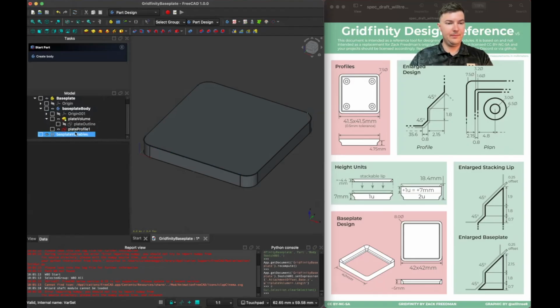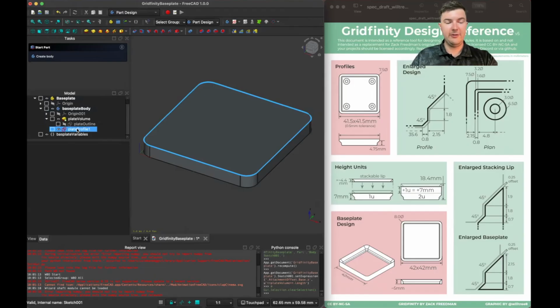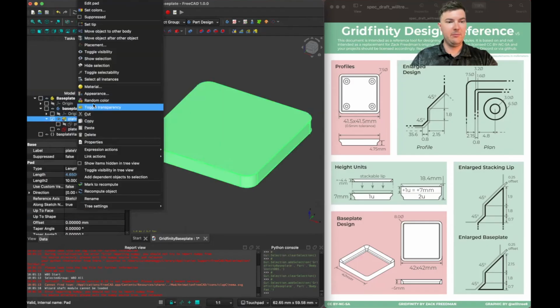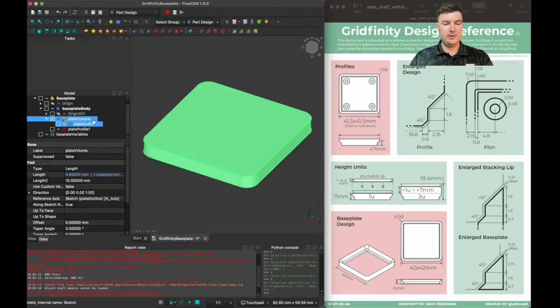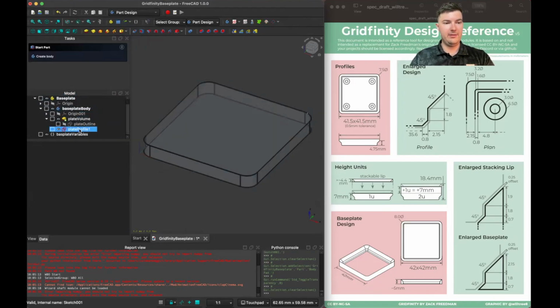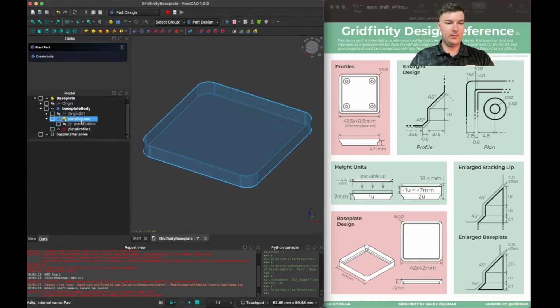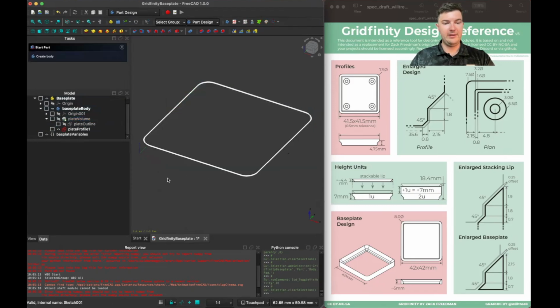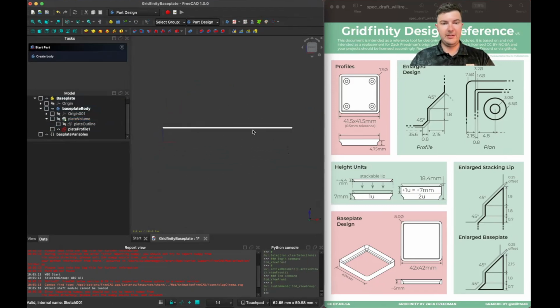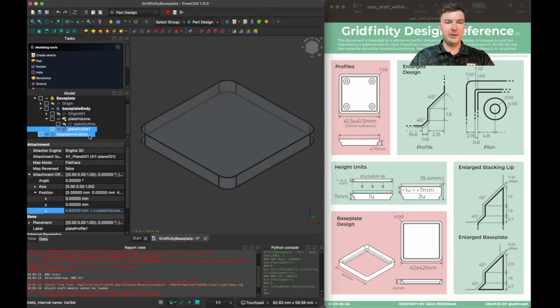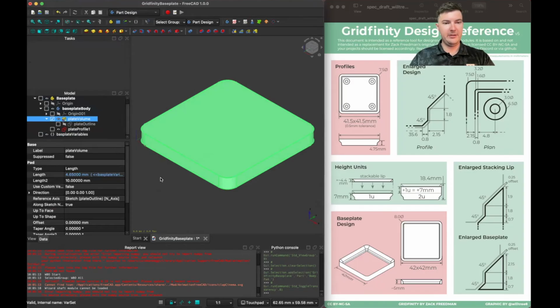So now we can see that that sketch is attached to the top of this face here. And I can verify that by pressing VT on my keyboard and toggling that transparency, or by pressing spacebar and hiding it entirely. And I can view the front plane and see that it's offset from the origin. So, press my spacebar again, go back to a nice ISO, and I don't actually want that to be transparent.